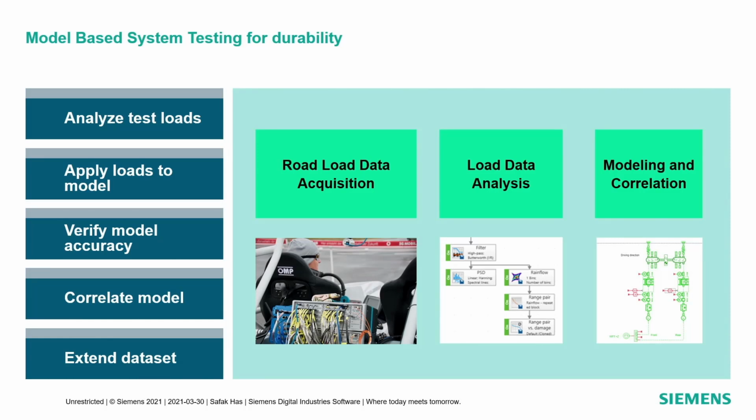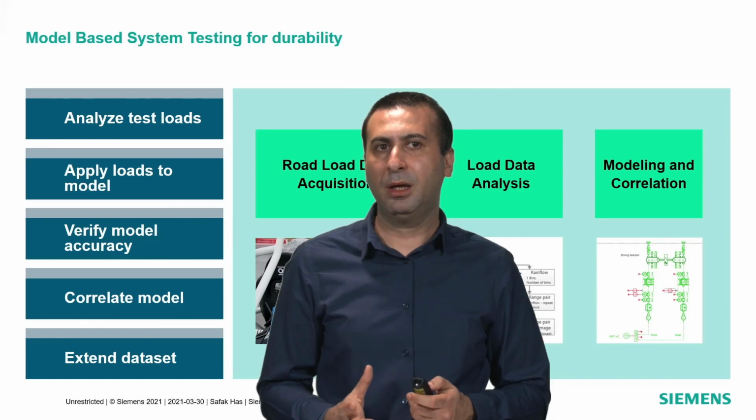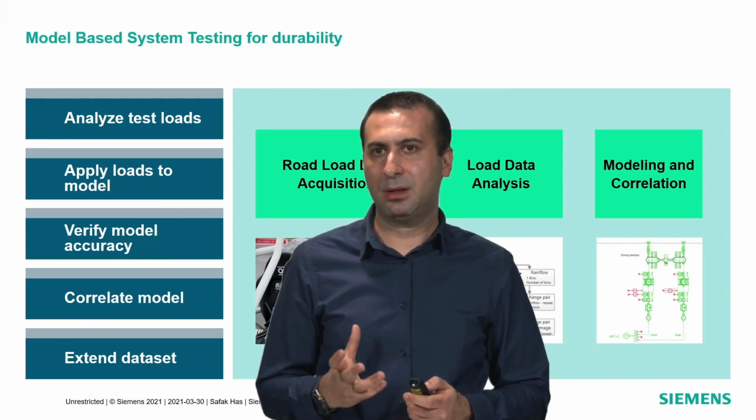So firstly, we will start with analyzing the test loads, because I'm going to also show you that I have 2 different surfaces in the proving ground that I could measure the data on. But it was very vital for me to understand the worst case scenario, to see which one was most damaging for me. So I will show you all those. Then we will see how we can easily import MSIM models via .fmu file into testing software, Simcenter Testlab.